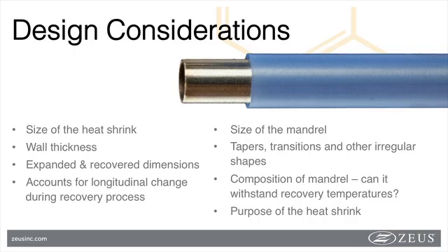What about composition of your mandrel? What temperatures can it withstand? Can you accommodate for slight softening of the material and potential dimensional change of such?